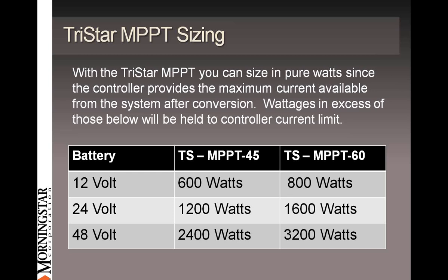It's just that you may not really get the benefit of those extra 300 watts because the array is just too big for that controller. It will very often, though, just run at full output pretty much all the time.